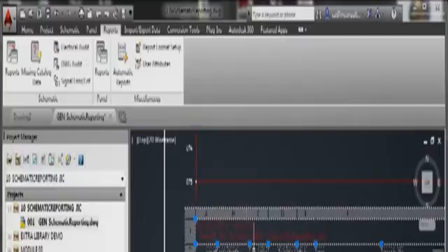This is actually an AutoCAD table. So if I do click on it, it responds in the same way as any other AutoCAD table does. But be aware though, you can update it. There is a link where you can update it in the project itself. So if I run another report now, I can update the information if I need to.